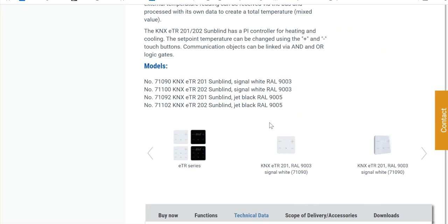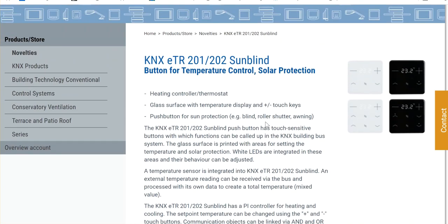Okay, so you should consider 25 milliamp for this device instead of 10 milliamp, and figure out which power supply you need.